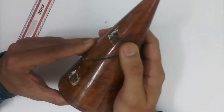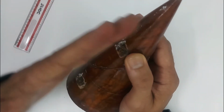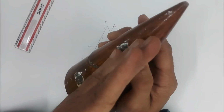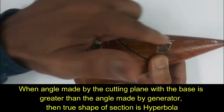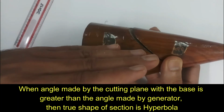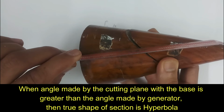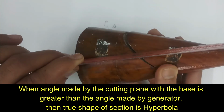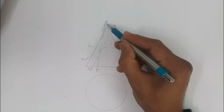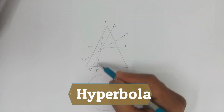Now the fourth possibility is something like this. If I cut this cone by a cutting plane which makes more angle than this generator. We can see this is the angle made by the generator with the base. So if I cut this particular cone by a cutting plane which is making more angle as compared to the angle made by the generator, then the true shape of section is a hyperbola. Section 4 4 is going to give you the true shape of section as a hyperbola.